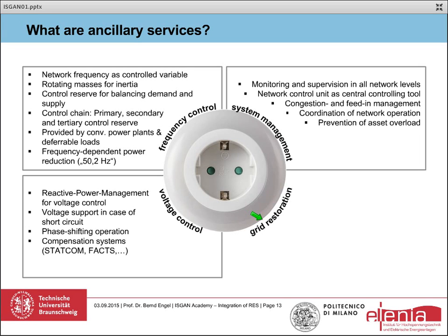System management is monitoring and supervision in all network levels, with the network control unit as central controlling tool. We have congestion and feed-in management, especially for renewable energy sources, coordination of the network operation and prevention of asset overload.